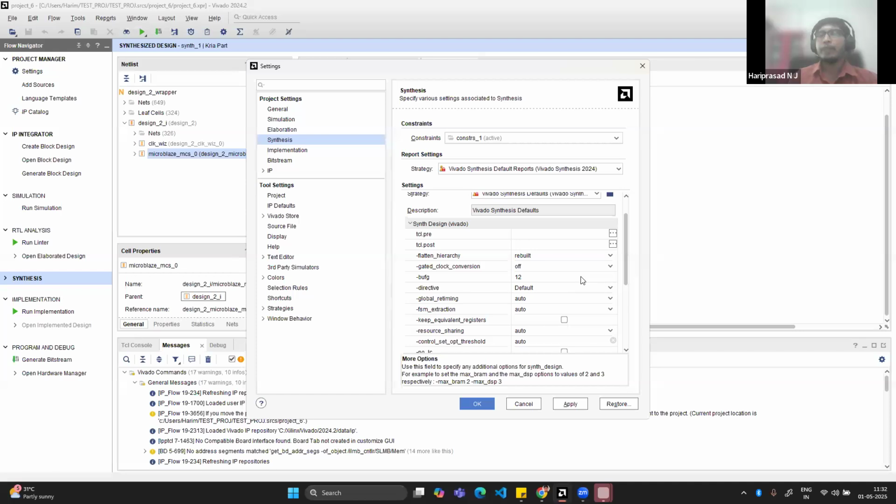Okay, and many a time in industry, we write various TCL scripts for what should happen before synthesis and what should happen after synthesis, right? So here, let's say there are a lot of warnings. We have written an automated script which, post synthesis, will analyze whether there is any error or any issue in the design, right? That TCL script automatically verifies, or else every time you synthesize there will be thousands of errors, and you have to analyze each error in detail. So that is not correct, right?